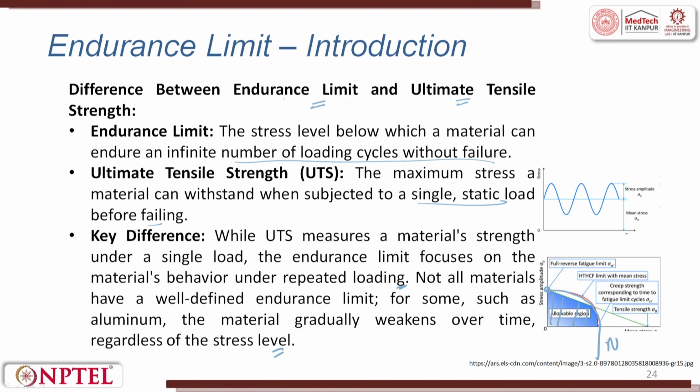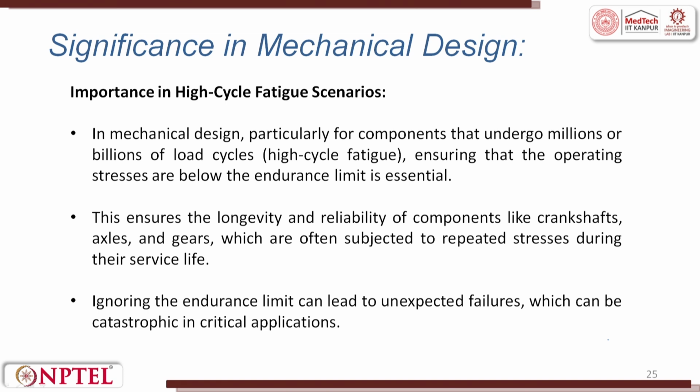and we choose the material. Importance of high cycle fatigue scenario in mechanical design, particularly for components that undergo millions or billions of cycles, is that it ensures that the operating stresses are below the endurance limit. This ensures the longevity and the reliability of the component. Ignoring endurance limit can lead to unexpected failure.